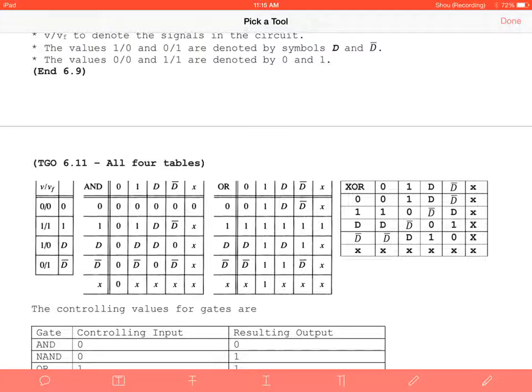If you have a 1 on one of the inputs and it's unknown, you're still going to get a 1 on the output. So the controllability of the OR gate is dictated by a logic value of 0. If you put a 1 on either input, 1 will be propagated to the output. The observability is not very good, because you can't propagate the error to the output. Does that make sense?